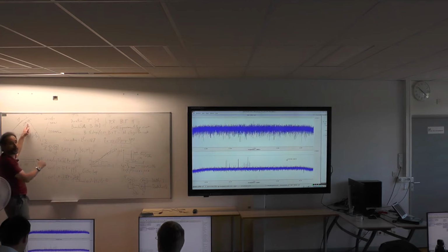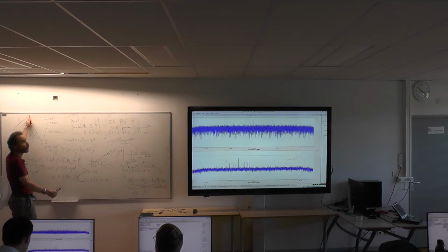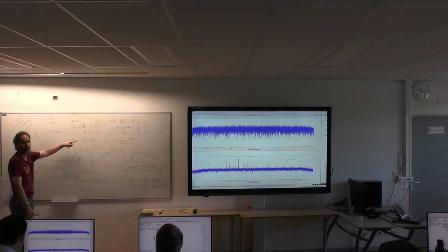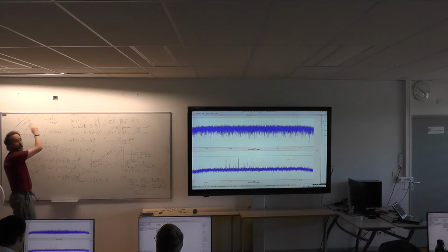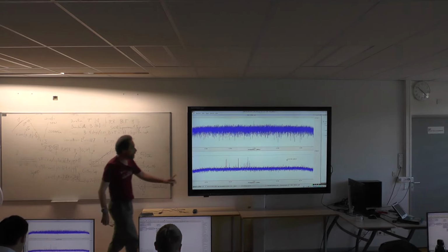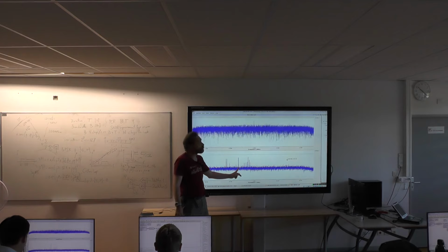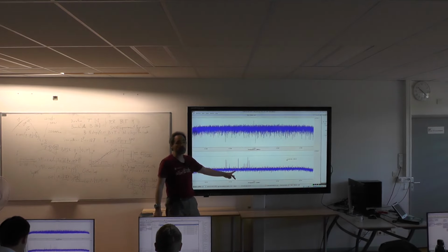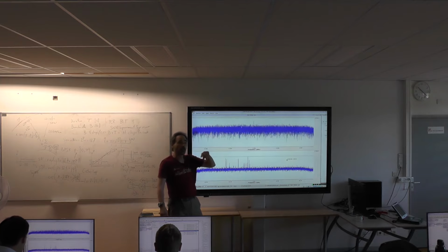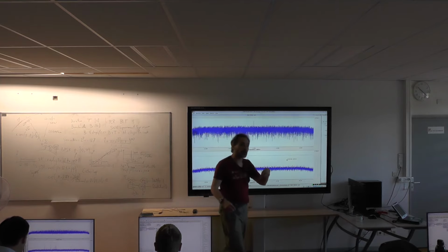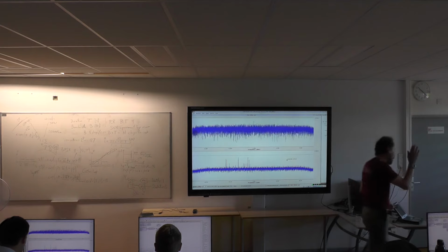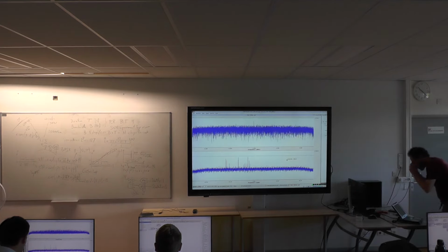Here you have something that is mean value 0. As many satellites are rising over the horizon, positive Doppler shift, as setting over the horizon, negative Doppler shift. But this guy is common to all the receivers. So basically what you see here is that I have a poor quality local oscillator, which is offset by about 5 kilohertz. Actually 5 kilohertz on the squared, 2.5 kilohertz on the original signal. Okay? So the mean value of a squared signal tells you what the frequency offset is.